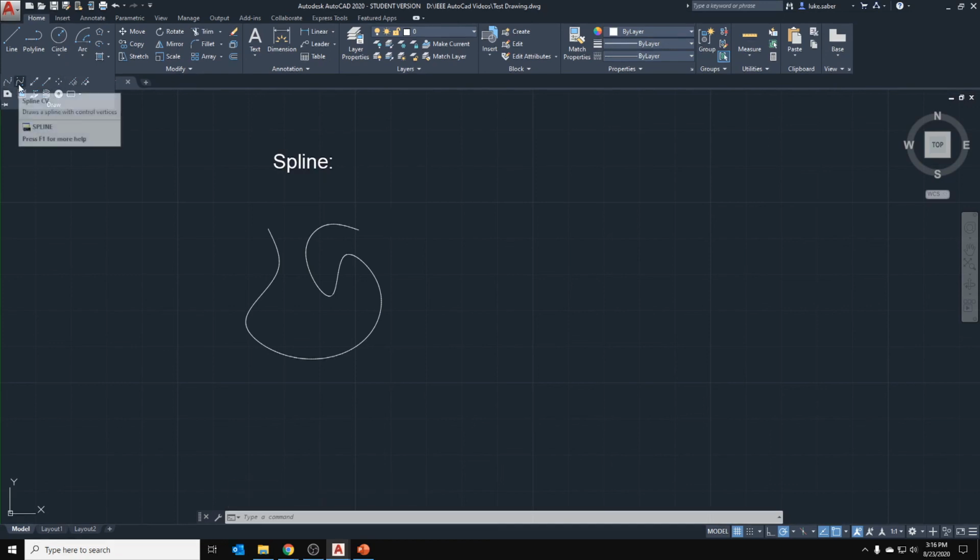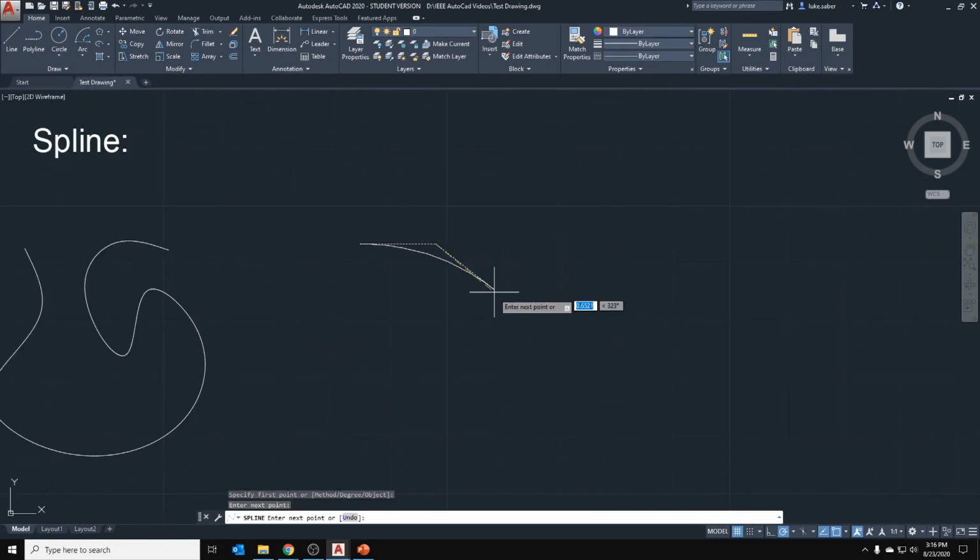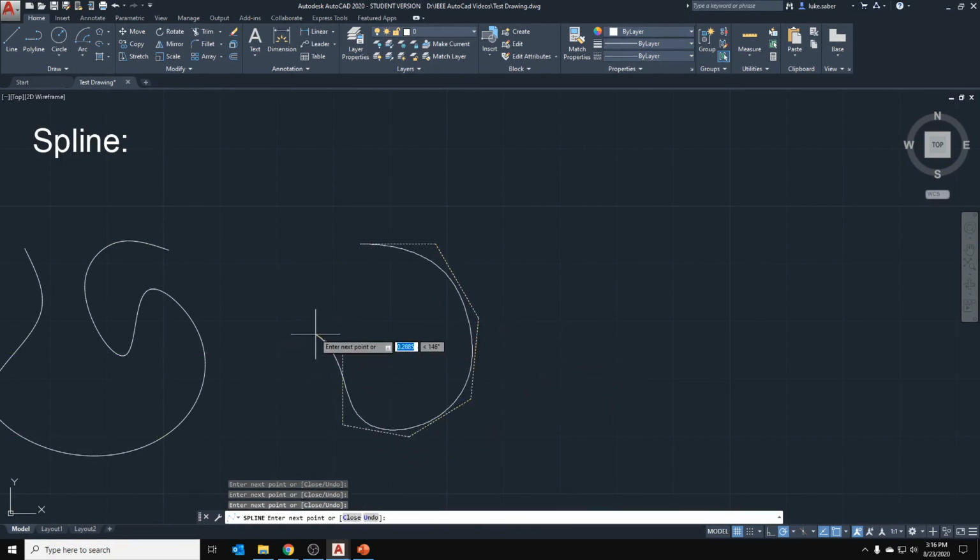You've got another one here, which is the Spline CV. We'll do that right next to it. It's basically a spline line, but it works a little different. It works with understanding the radius of where you're at, and it draws it out for you and leaves those reference lines that you're drawing until you actually click enter, like this. So they're there, and they go away when you click enter and submit the whole thing. But if you were to click it, you can actually still see them, and you can edit them.